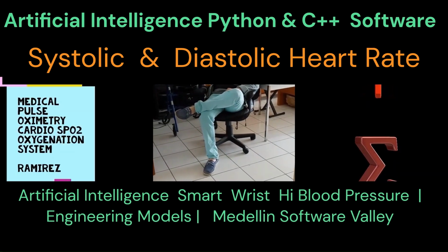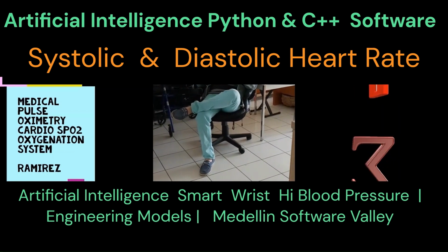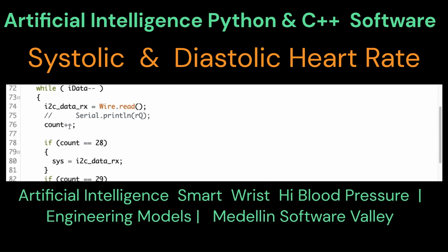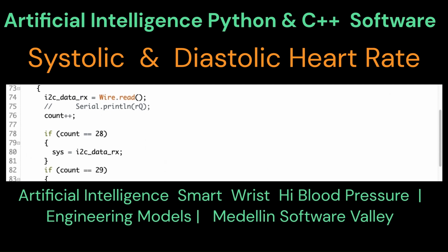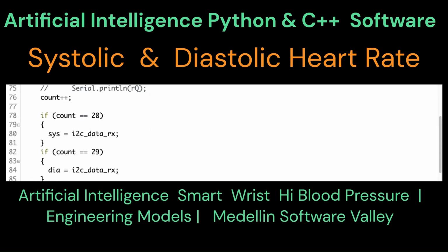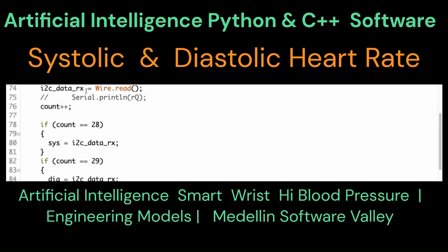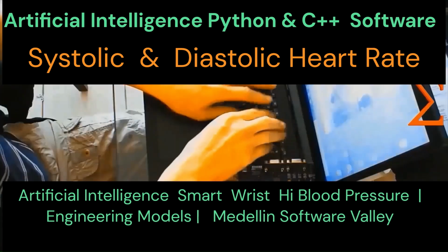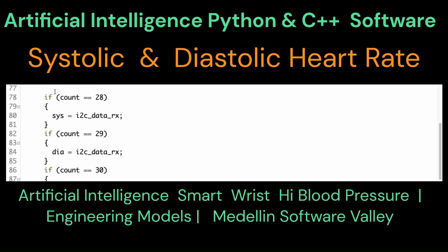I designed an automatic feedback algorithm for motor control, because an error in the analysis increases as the cuff pressure changes due to the patient's movements. Thus, an algorithm for estimating the optimal cuff pressure is developed to automatically control the driver motor so that the cuff pressure remains constant. The data measured by the pressure sensors are divided into pulse waves and cuff pressure using